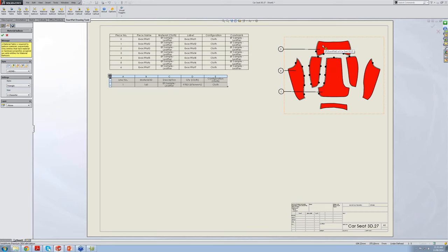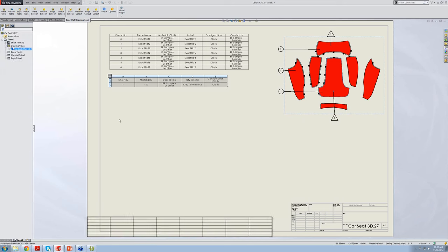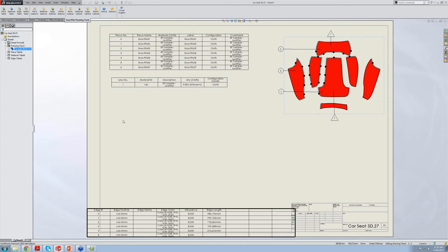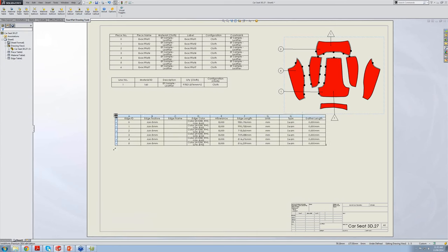So you envision industrial insulation covering, for instance. You envision a template elbow or a template T or a template type profile. And you just need to use the SolidWorks dimensions. You stretch, push, and pull a couple seconds to change the size of the model, and all of your documentation can just be updated. You just have to go through the process, and it just is all associated.